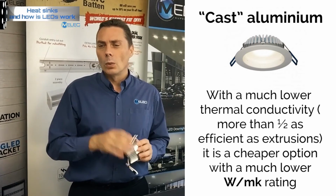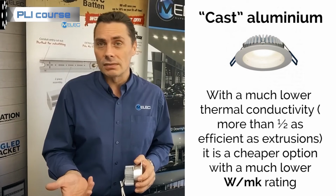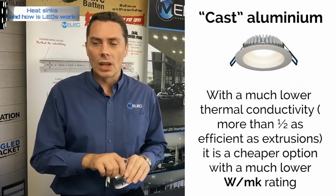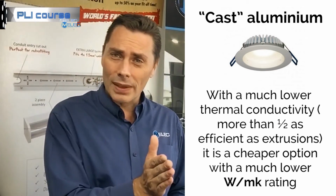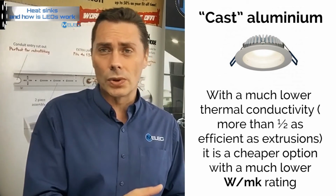The third option is the cast aluminium, which has a much lower thermal conductivity, less than half that of the extrusions. It is a cheaper option with a much lower W/mK rating. However, its purpose is there. It still does get rid of that heat, but just not as quickly and not as effectively as the extruded.